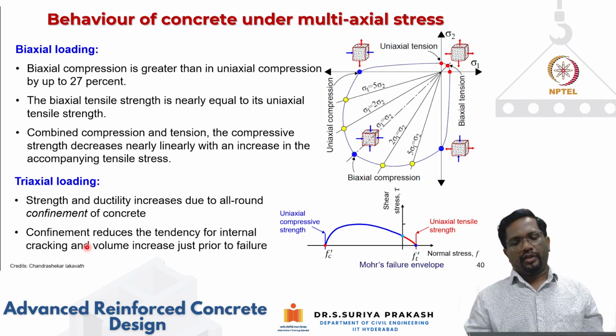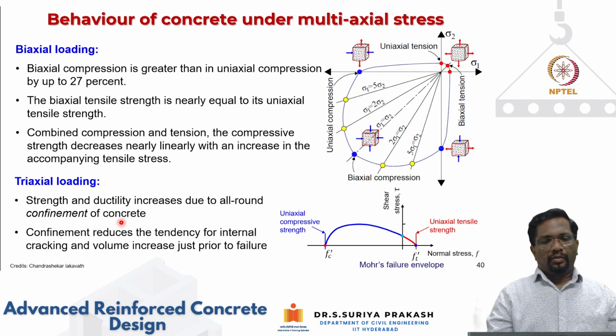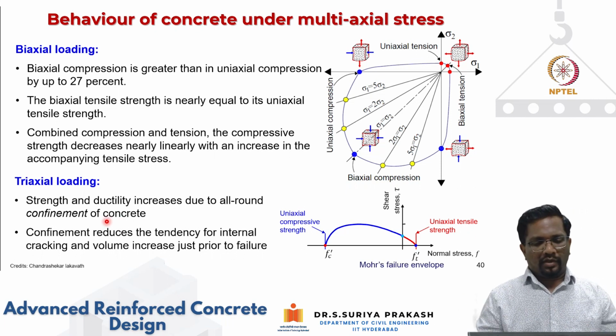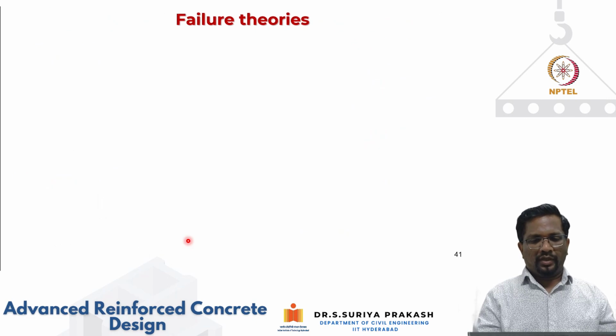After that, concrete will start dilating, right? But if you put this in confinement, it reduces the tendency of internal cracking and volume increase just prior to failure. So that is what happens in the triaxial stress state.